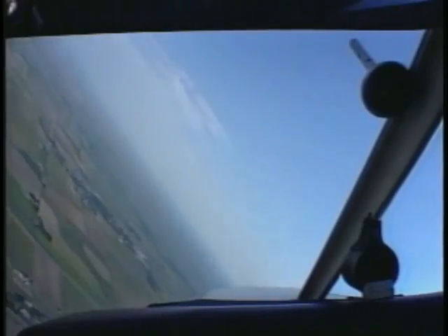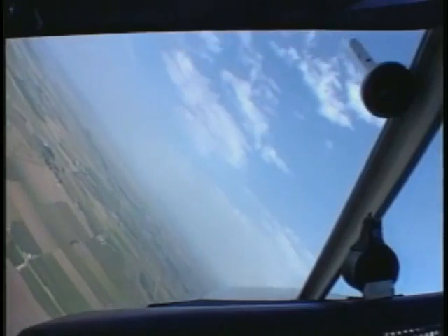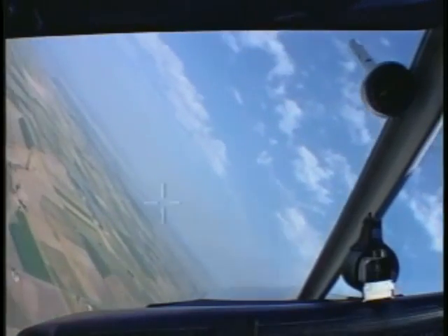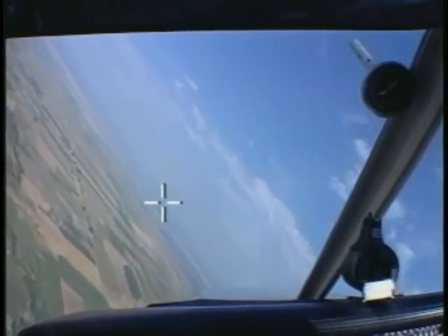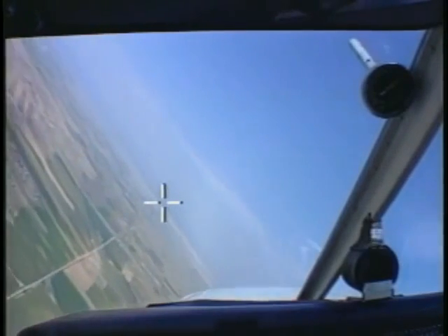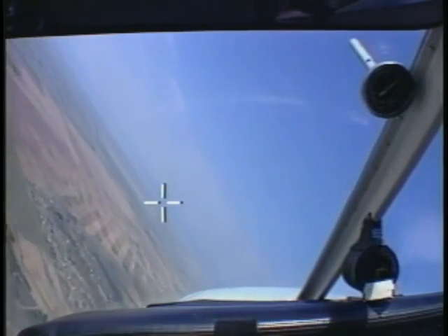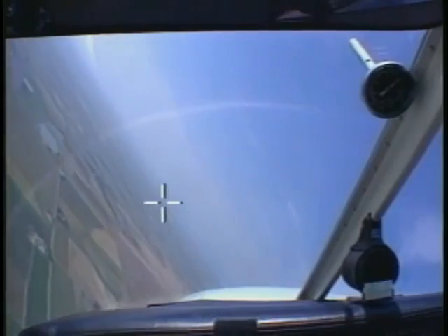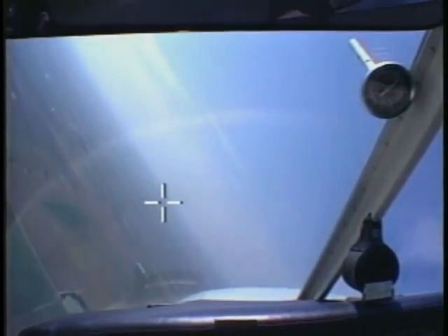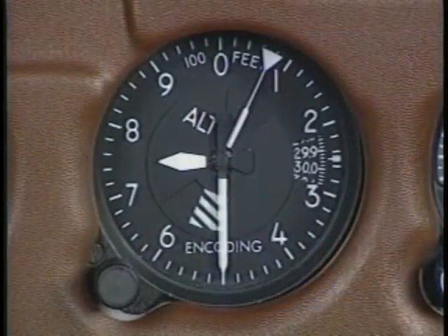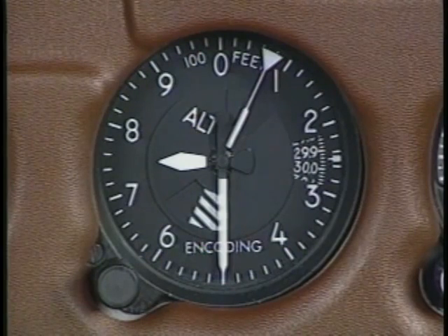One way to help maintain the proper pitch attitude is to select a spot on the windshield that is on a direct line between your eyes and the horizon. With a constant bank angle, you can determine proper pitch attitude by keeping the spot aligned with the horizon. Be alert for anything that might affect your altitude.